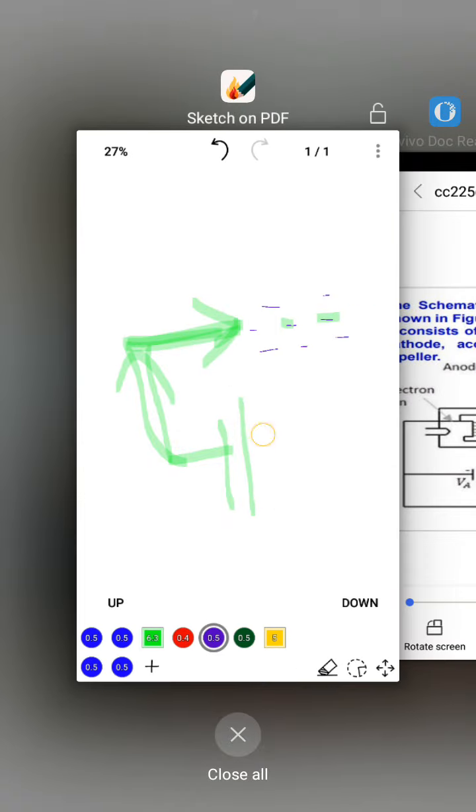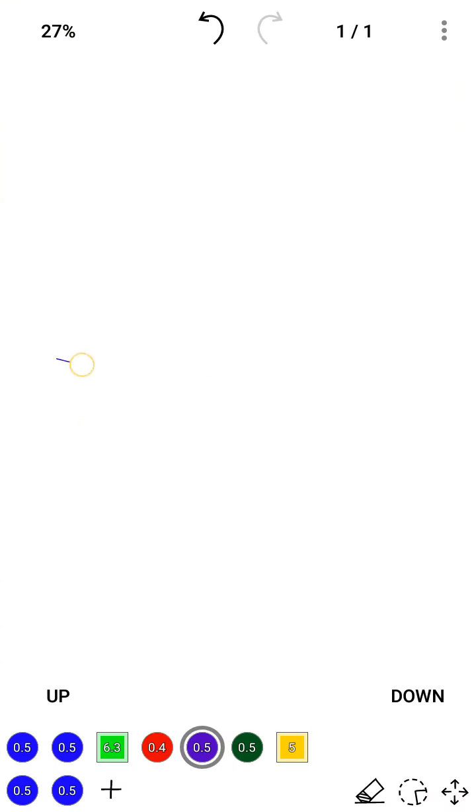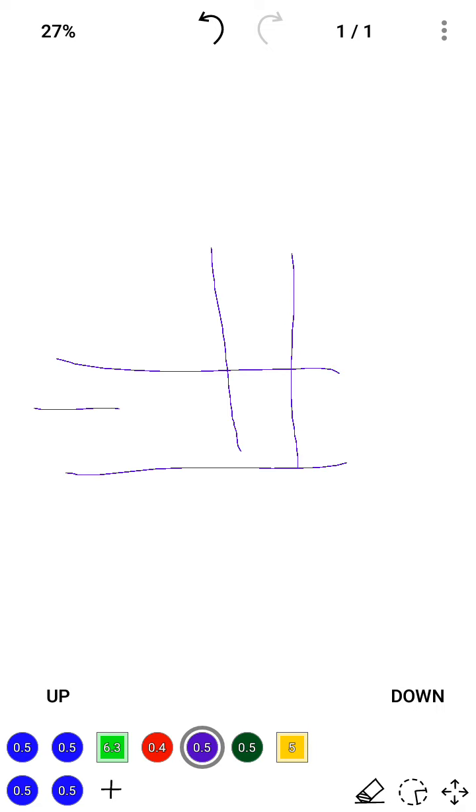I'll explain clearly here. Assume this is the cavity and this is the electron gun producing electrons. The electrons are produced up to the cavity and travel at a constant speed, but the cavity contains a resonant signal like this sine wave. Now the velocity modulation process gets started.